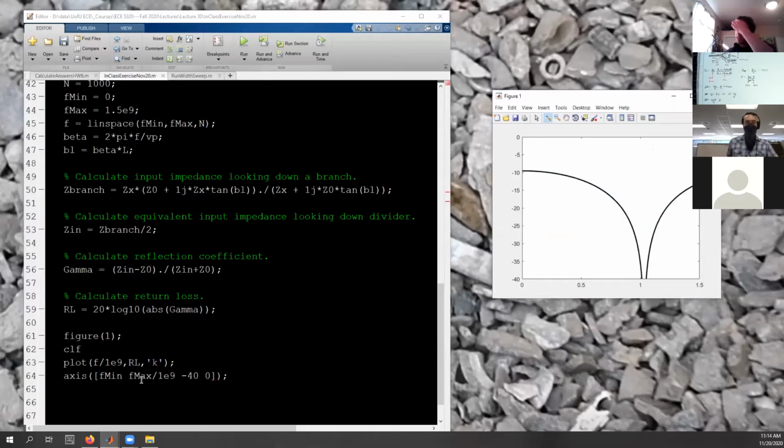So that's a nice way to think of it. That's what a typical return loss for a Wilkinson power divider ought to look like. And you can see it's in the textbook there too. It gives a nice simple value, only they use normalized frequency units. Sorry, they also plot all the other S parameters, an S12 and an S23 in there as well. But this is all we've cared about for now.